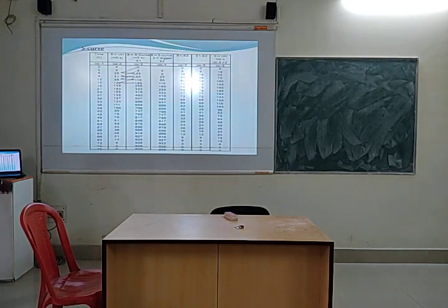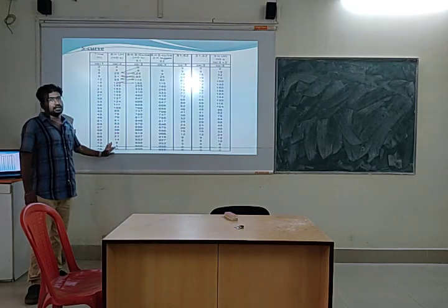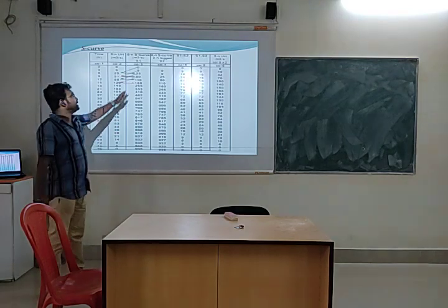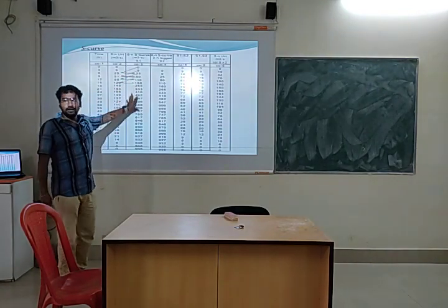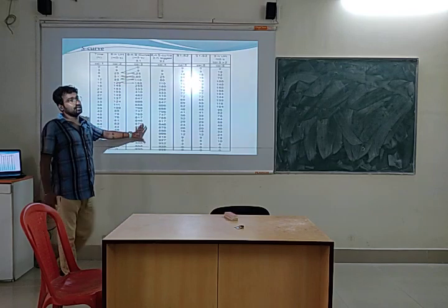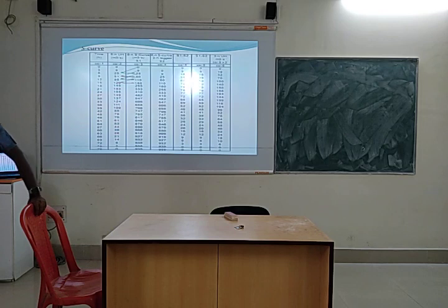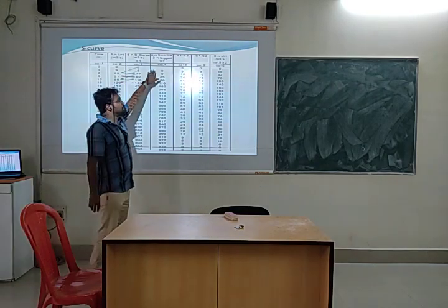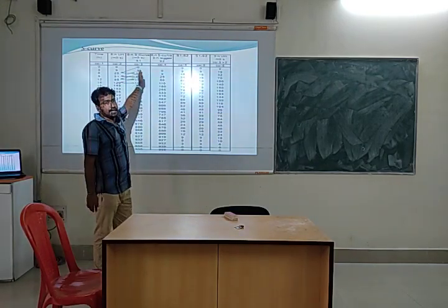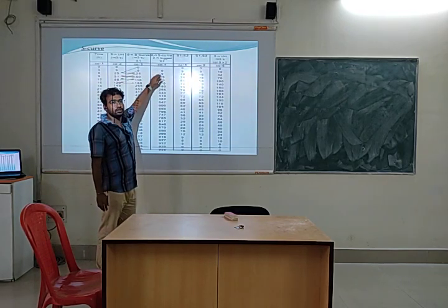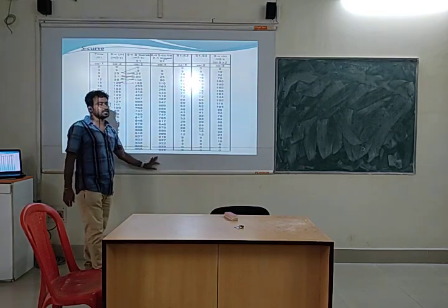So the basic funda is the same. After finding out those things, the procedure will be the same, right? So you have to first find out the 6 hour S curve. Then you have to find out another S curve that will be lagged by T hours, where T is the time duration for which you are trying to find out the unit hydrograph. So this will be lagged by 3 hours, right? So S1 and S2 will be lagged by 3 hours. After 3 hours, it will start from zero, and all the data will be the same. It will just lag by 3 hours.